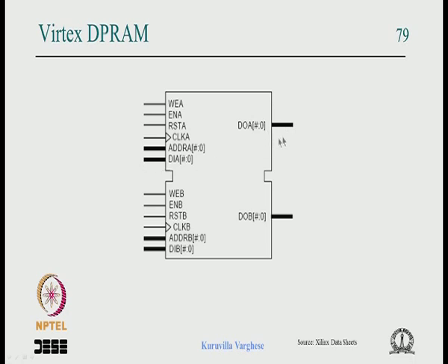separate, which is true of every memory chip, because you can imagine the memory cell inside, or you want to assume the flip flops inside in each location, and the data input is the D of the flip flop, data output is the Q of the flip flop. Only thing is that there will be multiple locations, depending on the location you want to read, there will be a mux there.